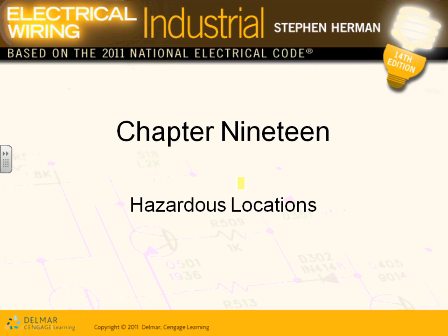Location, the building that we have, our building, which is a 25,000 square foot industrial building, we have a room that's a Class 1 Div 1 location, so we are required to have explosion proof equipment. Hazardous location, if you work in the manufacturing area, a lot of manufacturing areas and certain areas of the commercial building will have some type of a gas or a dust or flares that could ignite the surroundings.